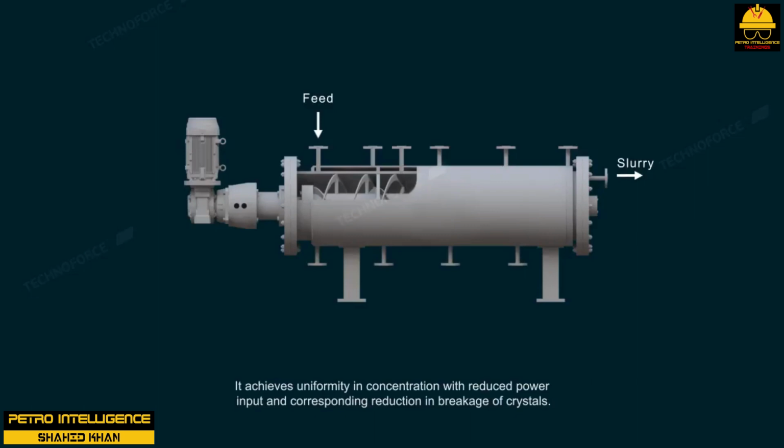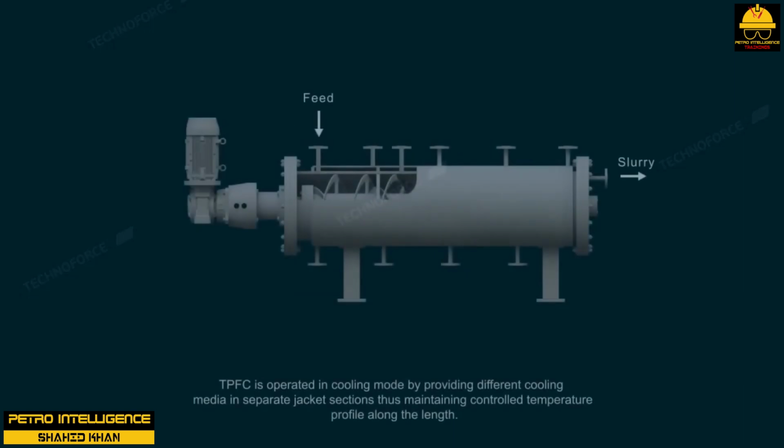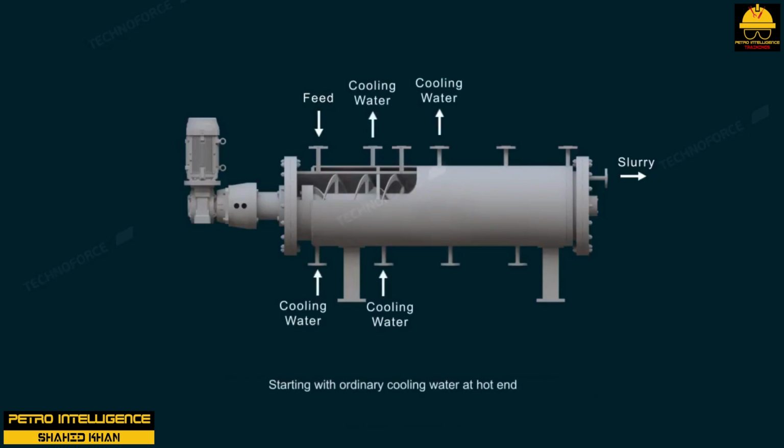Crystal growth is a very complex phenomenon, and many outside factors affect it, including the starting temperature, the starting concentration, the amount of mixing or lack of mixing, the rate of cooling or evaporation, contamination, and the presence of smaller crystals. The crystallization process can be either batch or continuous. The size of the crystals is controlled by adding liquid and removing crystals.